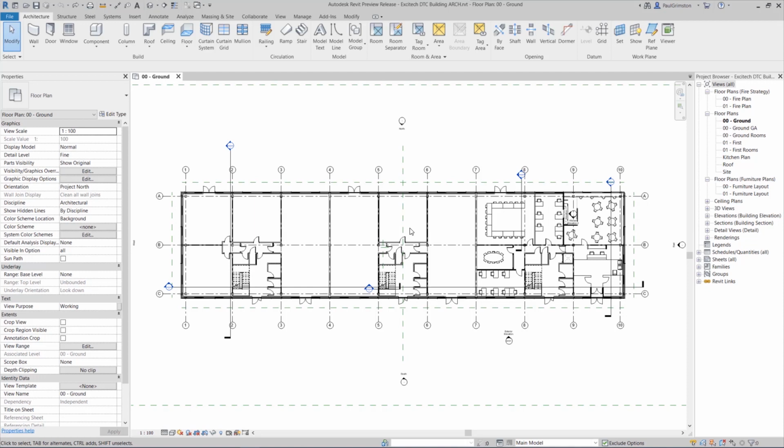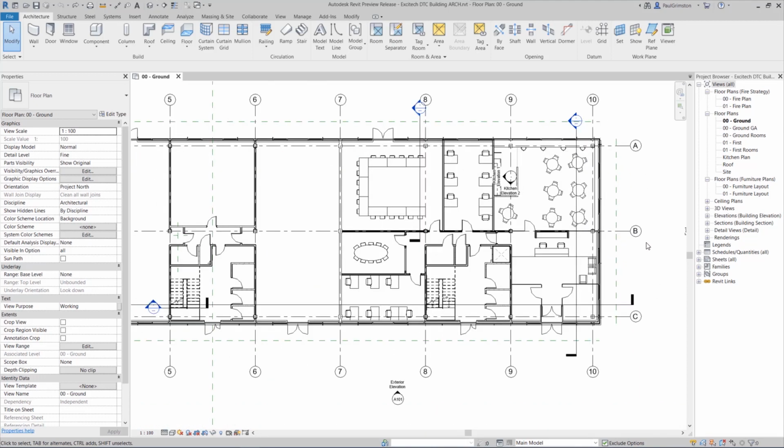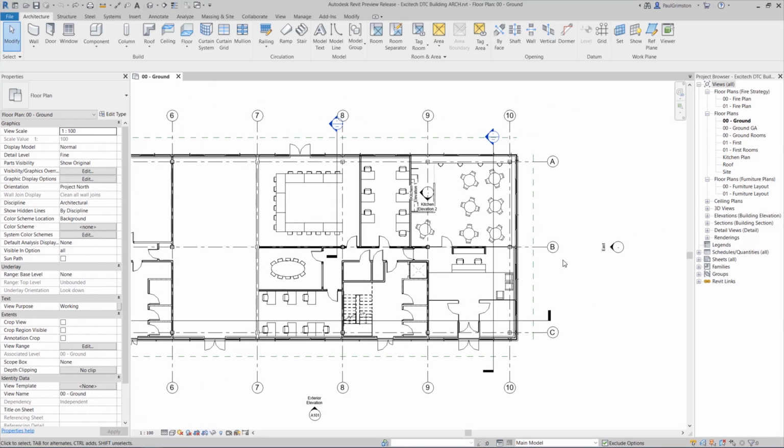The next feature we're going to look at in Revit 2020 is the path of travel analysis. This tool enables us to plot the path between 2 points of our choosing within the building. It's going to be useful for things like fire escape routes, and in plotting these, it automatically does the routing for us and then works out the time it's going to take to travel along that path. So it's quite a useful tool. We often need to show our escape routes on plans and things, so it's going to save us some time and be quite useful in doing that.